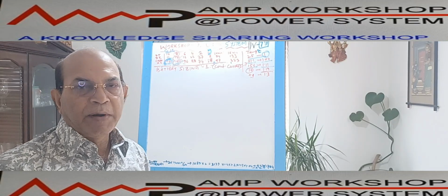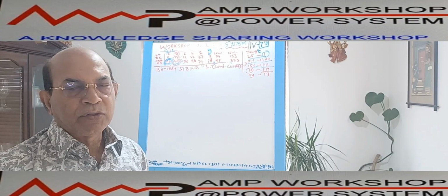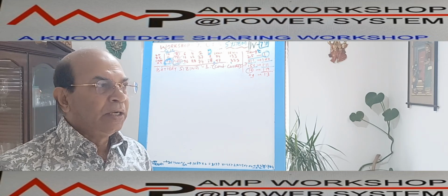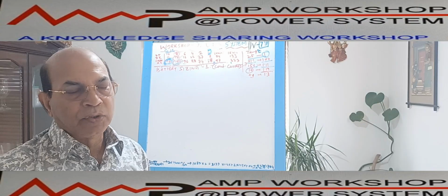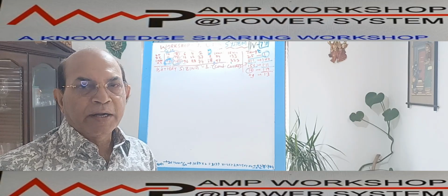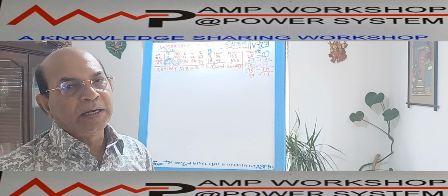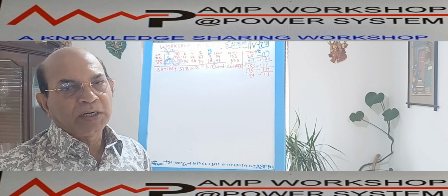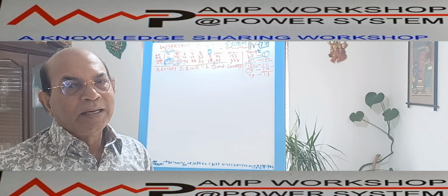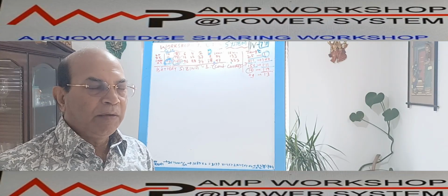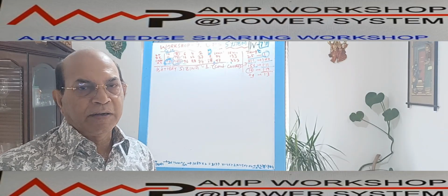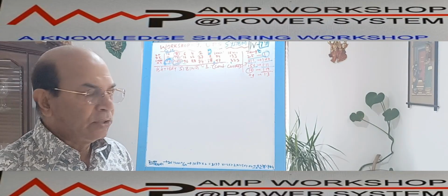The other type, the nickel cadmium battery, is also widely used. Whether we use a nickel cadmium battery or a lead acid battery depends on various parameters of the load. The advantage of the nickel cadmium battery is that its life is long, and it can deliver at constant voltage for a longer time than the lead acid battery. With a lead acid battery, after discharging for a certain time the terminal voltage drops, so the load cannot get the required voltage. But if you need a long duration of constant voltage at the load, the nickel cadmium battery is the greater preference. We will discuss all these things in detail.